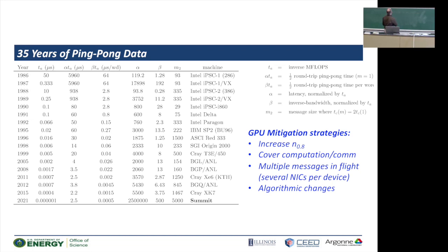So here's the measured latency on this. Now on this chip, the latency is gated by the CPU, which is running quite slowly. So when we accelerated it, going from the 286 to the 386, the latency time came down by that ratio roughly, actually in this case, factor 6. But the relative latency, when you added the accelerator, was huge, 18,000 versus 120. And now down here, 3,700 versus 93. It's not that these numbers are good or bad, it's just that they're different, and you make different design choices accordingly.